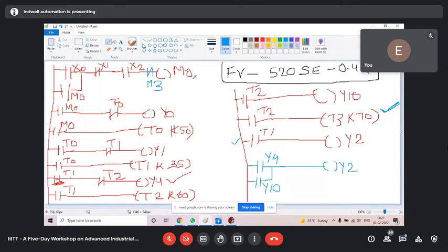In that case, do not break latch. So you see, I have removed it. How to repeat? To repeat the process, take the last signal. This is the last signal, T3. Take the last signal, break first timer. Don't break latch. But if you break first timer, it will repeat the process.